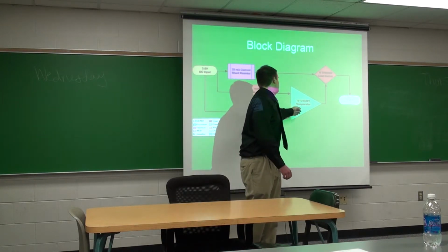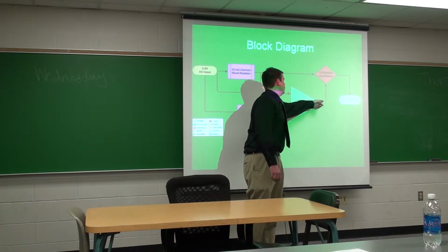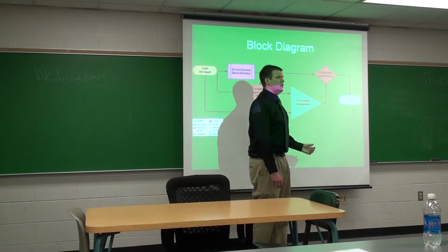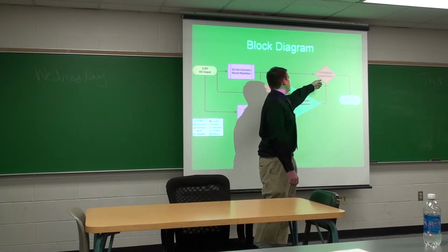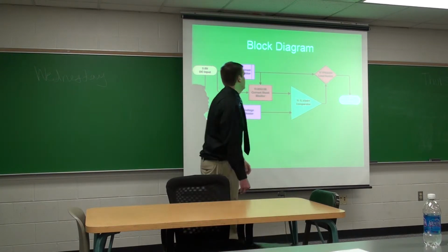So if this is higher, it's going to output a low voltage here. And when that outputs a low voltage, the TI load switch is going to open and cut power to the load.